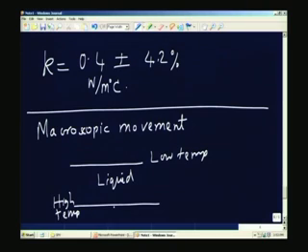Normally, at a high temperature the density is smaller, and at low temperature the density is higher, and therefore the liquid will be lighter near the hot wall and it will tend to move up, and then of course the colder liquid will come downwards. So, therefore, you expect some kind of a motion like this, up and down motion. So, this is referred to as natural convection.